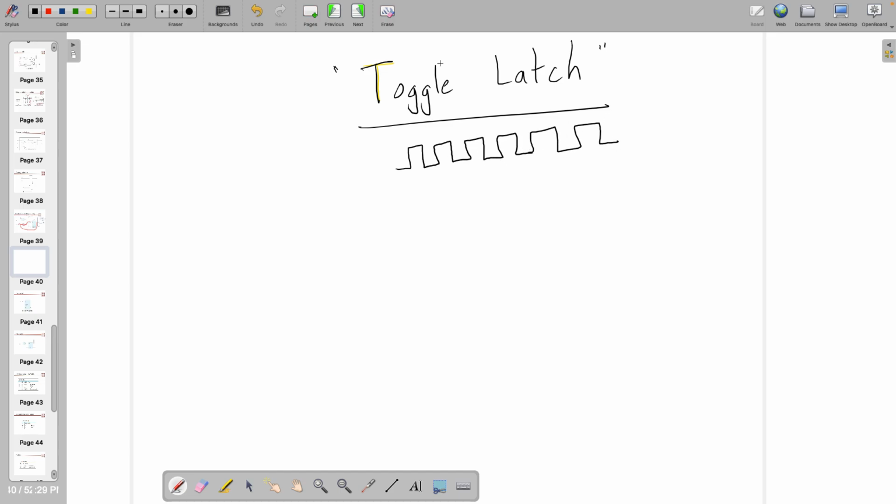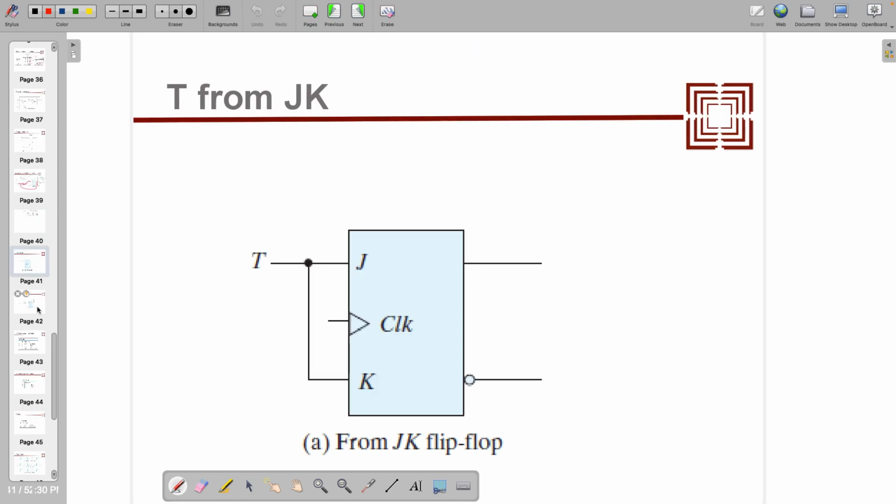By the way, because of toggling nature of the output, this is known as T latch, right. So if I want that, how to get it, right. So if J and K both are 1, if inside that NAND gate based configuration is there and clock equal to 1, if all 3 are 1, output will toggle, do you agree with this one, right.